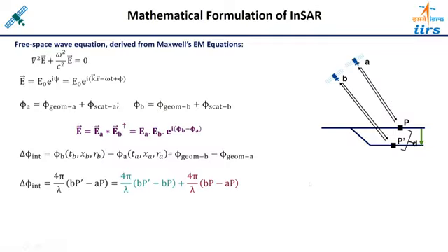It means a similar situation is happening over here. BP minus AP means both the satellite positions are looking towards the single target without deformation. It means they will measure the topography of this particular region. So you can say this particular term is called the topographic phase. This is called the deformation phase, and now this is interferometric phase.